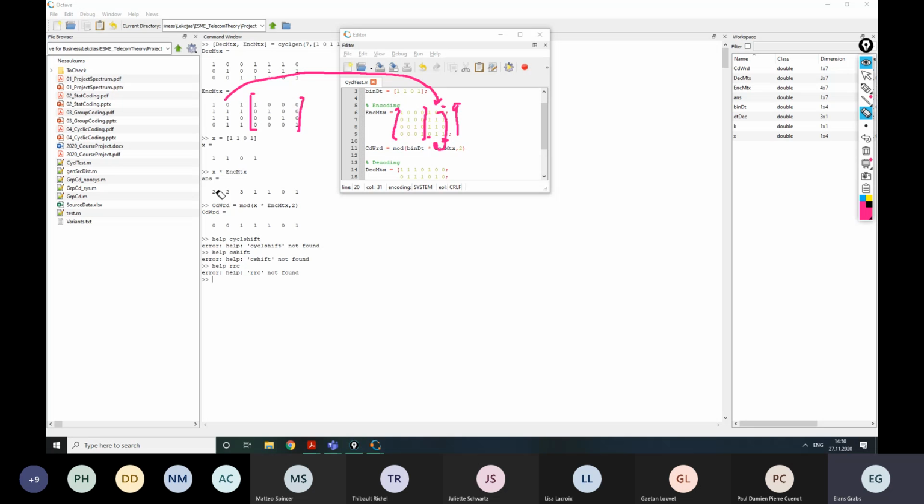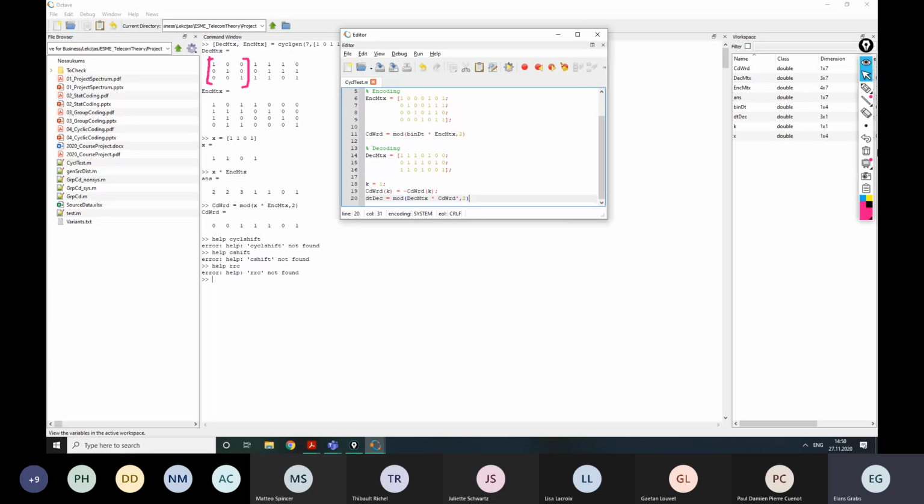make sure that you realize that the control bits come first in this solution. Similarly, I have rearranged the matrix for the decoding device. Also, here is the identity matrix, I matrix, which I have put at the end, since that's where my control symbols are. And here are the same generator polynomials, only shifted. So my generator polynomial was 1011.